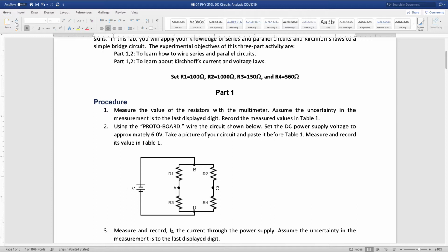Yeah. So for example, for part two, I used the smaller multimeter to measure voltage values. For one of the resistors, I would get values of 2.75 volts or 2.76 volts, and they would switch regularly. Just between those two values? Yeah. So I would just say 0.01 volt is the uncertainty, right? I mean, that's how I would look at it.